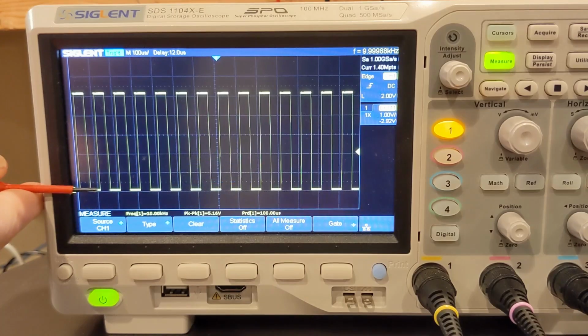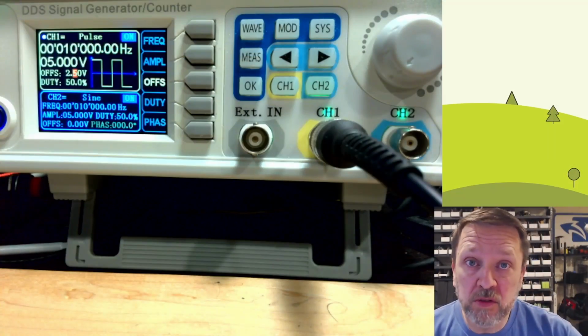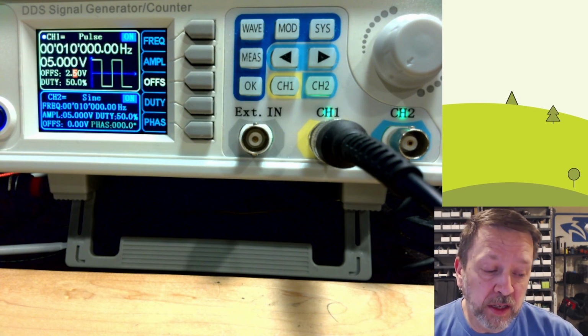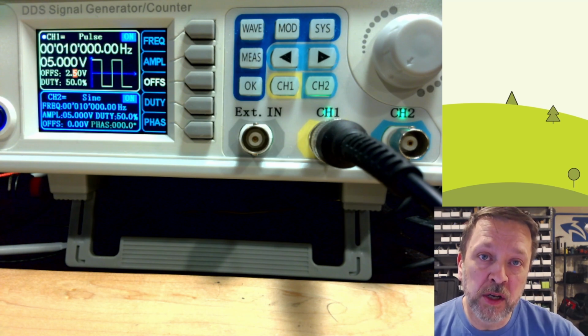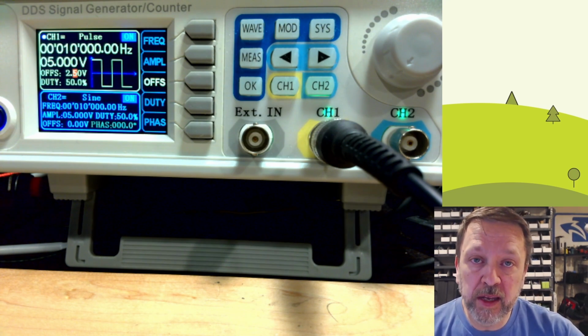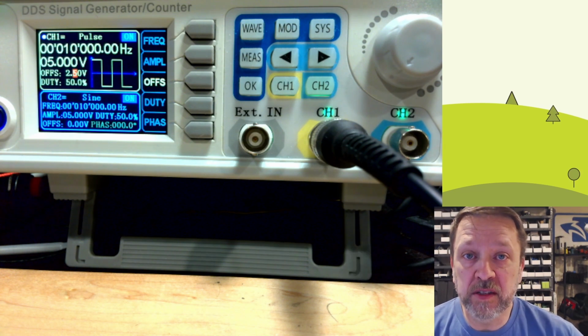So now our 0, again, is here, but it is at the base of the wave. And then our top is up here at 5.16 volts. That 5.1 volts is very important. When you're working with microcontrollers and embedded devices, they typically have a maximum voltage. Oftentimes it is 5, sometimes it's 3.3. It's very, very important to know the voltage range that is acceptable as an